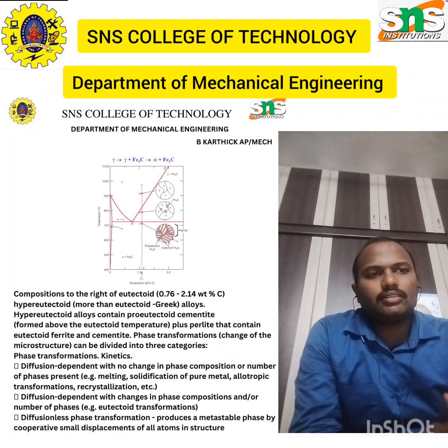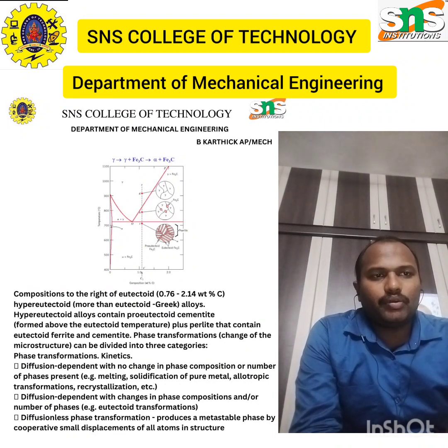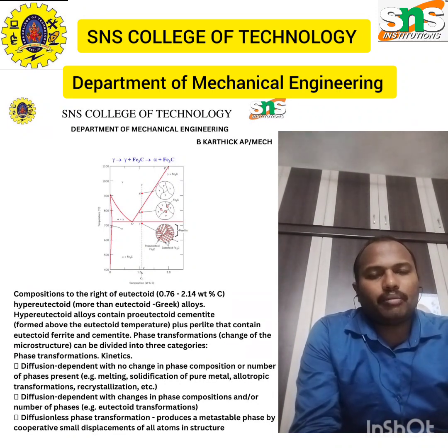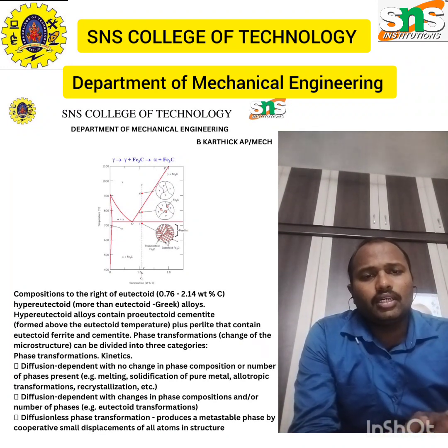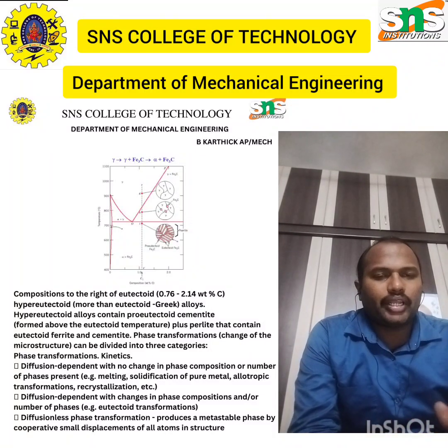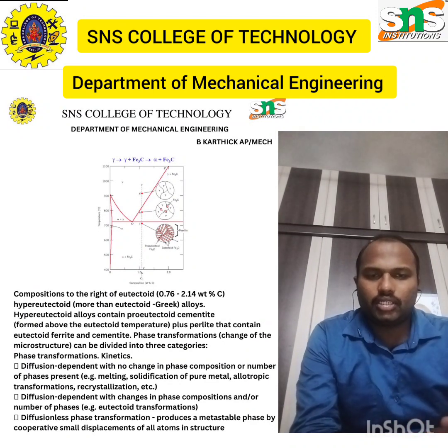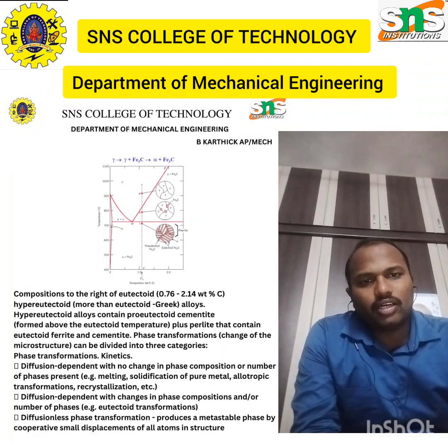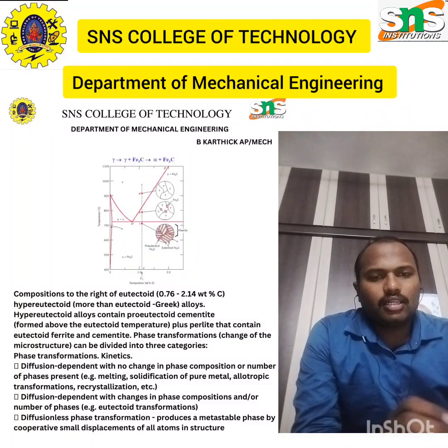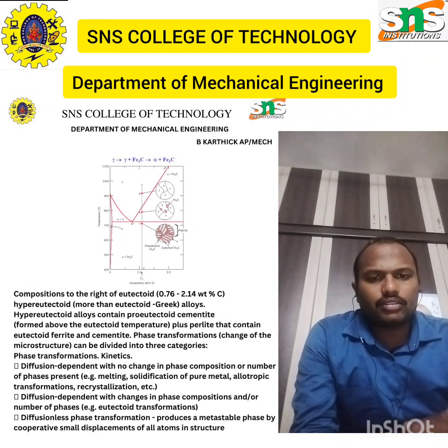So the next thing is that austenite is the only thing that is going to form. When we slowly cool down, in the microstructure you can see grain boundaries between the two grains. So here this proeutectoid alpha usually forms at the grain boundaries of those austenites, and upon cooling, this proeutectoid alpha is forming a pathway as it grows on, or as it propagates while the cooling is happening.